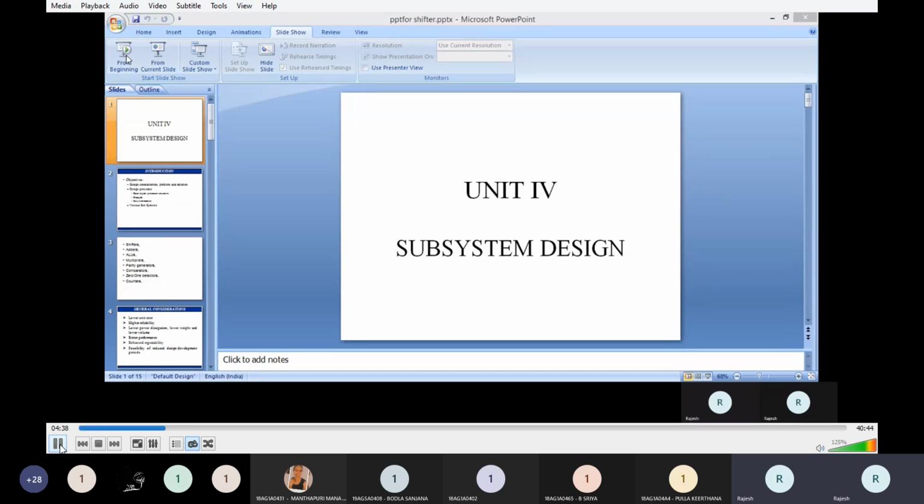Inverter implemented with only NMOS, with CMOS. CMOS means you have both PMOS and NMOS. Then, with a CMOS at the load side, you have a BJT in order to increase the output drive current. So that is your BiCMOS inverter. So this covers unit 1.